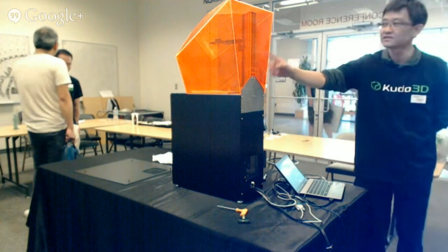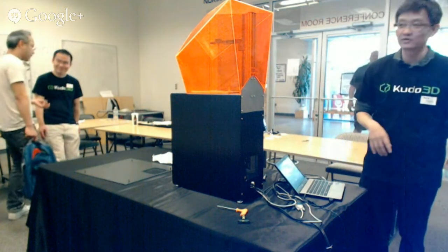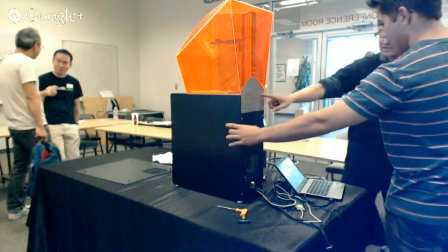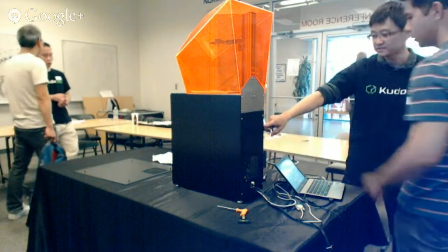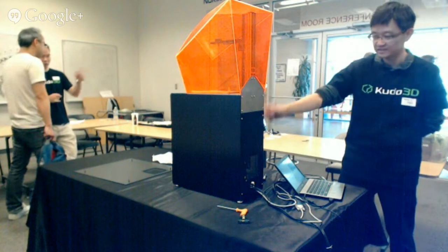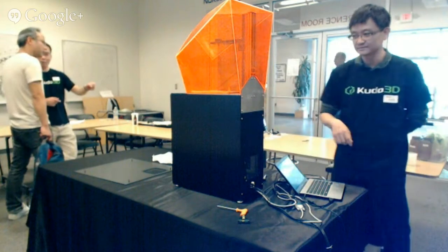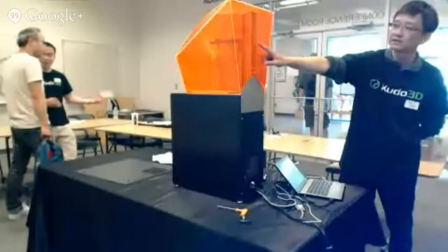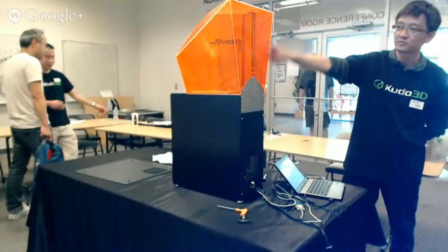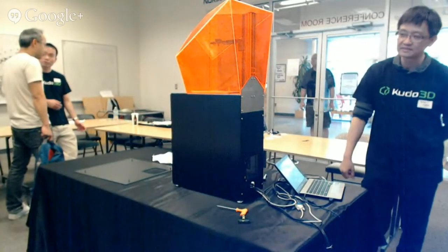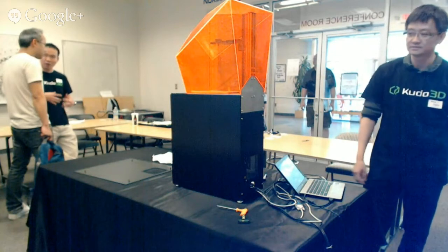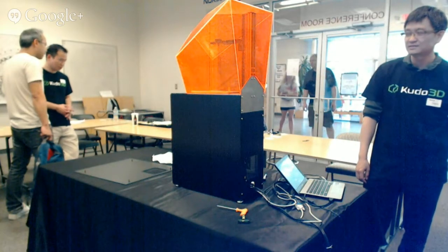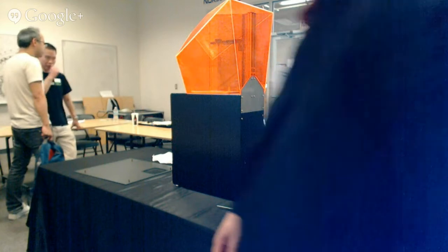In theory, the vat floor distance is not the same between different vats, because almost all vats are flexible, but also they're hand poured. And so they might not be... You're exactly talking about hand poured, like the B9 one. That's a film. So is there any board on that? Yeah, there is. There's silicone underneath it. Oh. In order to enhance the release, there's silicone under the film, so that the floor is not so rigid, so that it will move.